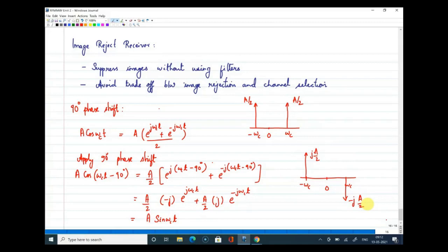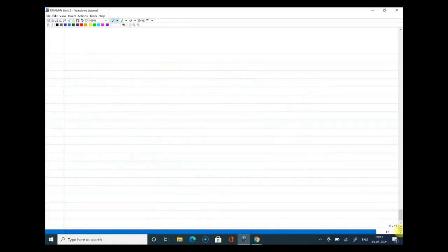Now, what we will do here is, by looking at the cosine and sine wave components, we realize that the amplitudes have both real and imaginary components, right? For the cosine wave, it is purely real, a by 2, a by 2, and for the sine wave, there is an imaginary component, which is j a by 2 and minus j a by 2. So I am translating this into a plane where I can mark the real and imaginary components versus frequency.